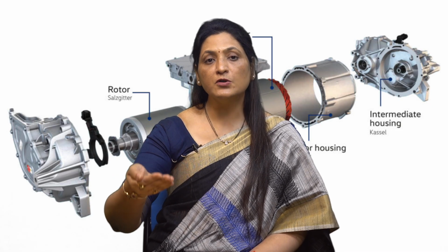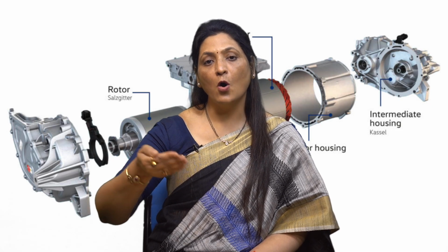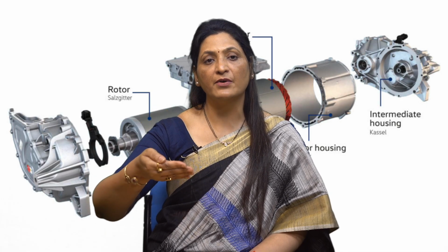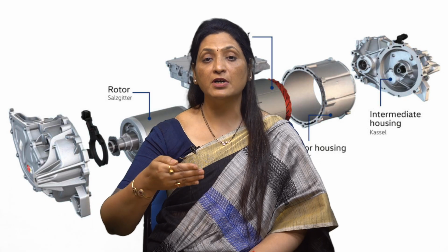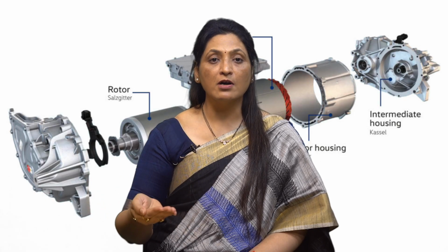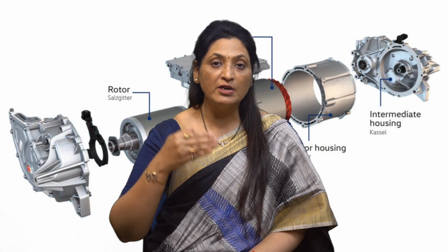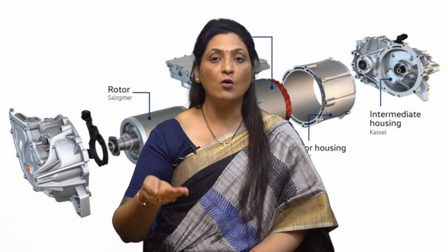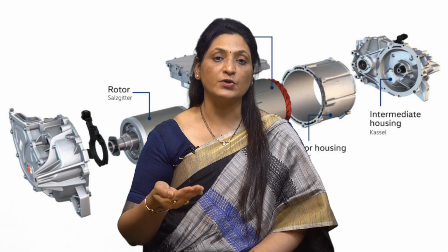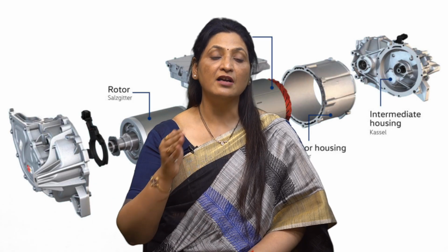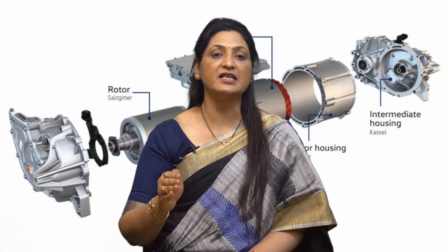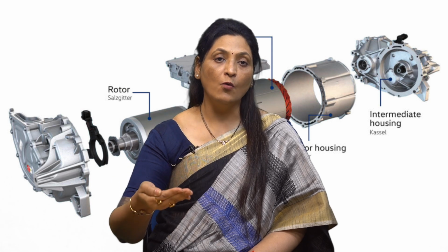Continuous operation near or at the motor's maximum power rating can lead to thermal overload if it is not properly cooled. This could cause motor failure due to insulation damage, bearing failure or other heat related issues. Therefore, the power rating should include a safety margin to handle occasional peaks in the load without overheating.